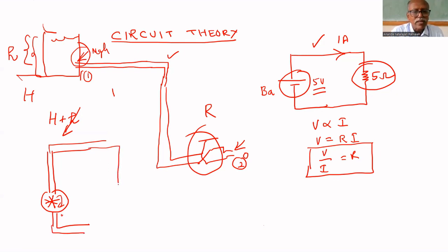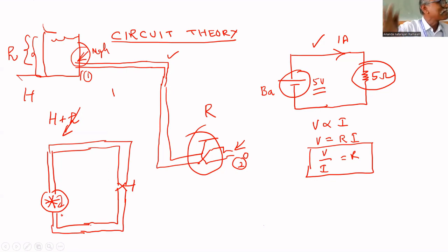So here I am putting one hand valve. This is the hand valve. This is the symbol for hand valve. That's why I'm using that. I'm connecting this way. Assume that the tube is filled with water. If you turn on this pump, it will rotate and it develops a negative pressure here. That's why the water in the bottom side will go to the point 2. Am I correct or not?